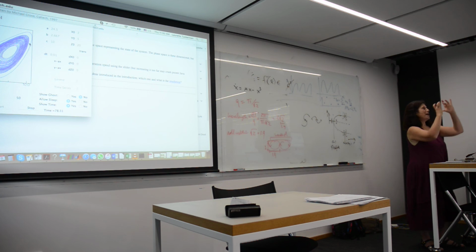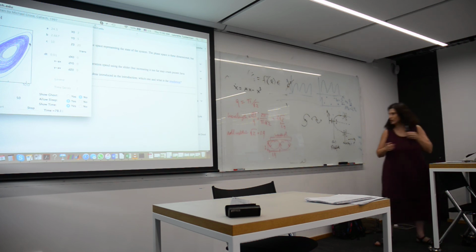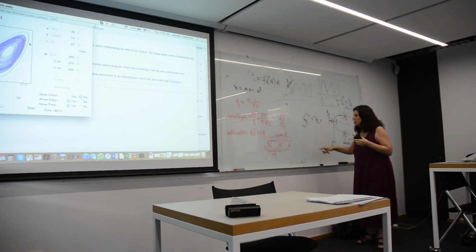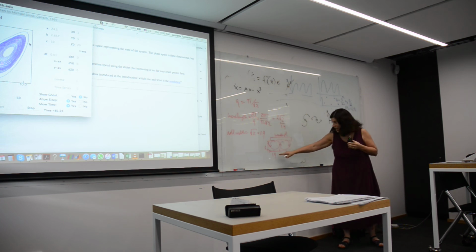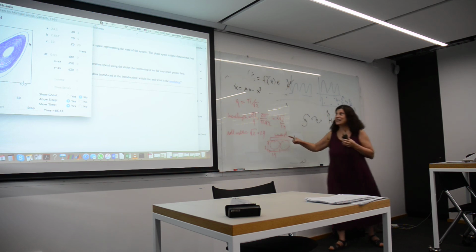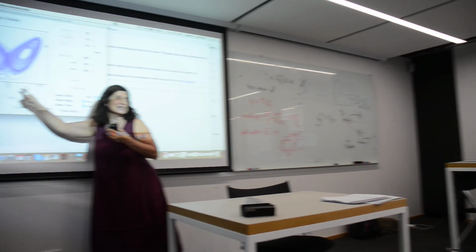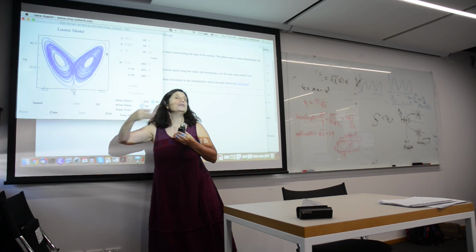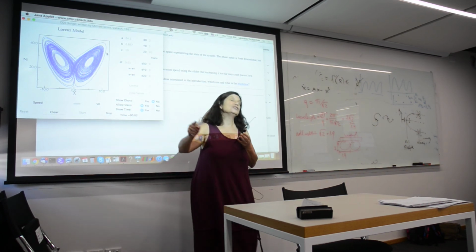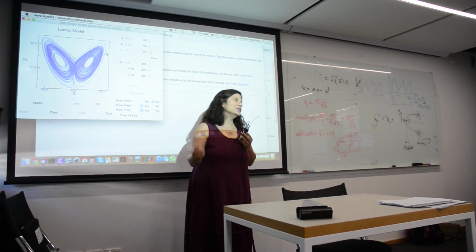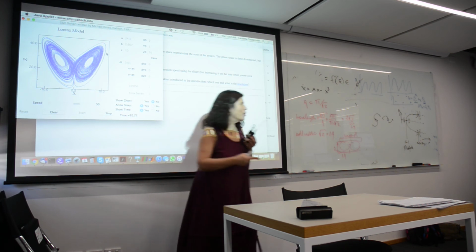So the rolls are always the same, the picture of the convection is the same. You're not allowing it to do anything other than this. Indeed, we still have that aspect ratio, that 1.4 that came from the free slip boundary conditions, and this is what it looks like. What's changing is these arrows. The arrows show the directionality, which is decided by the positive or negative X, because X multiplies psi, which is the stream function, and stream function being positive is counterclockwise and negative is clockwise.